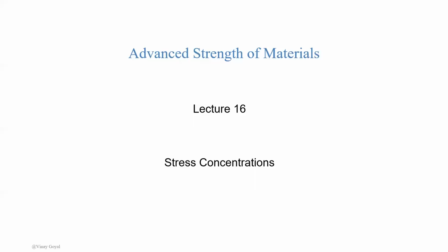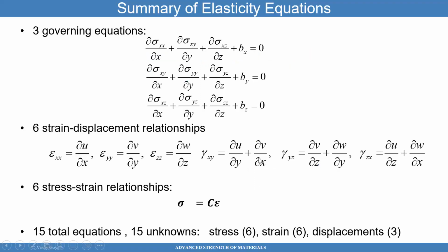We're gonna cover stress concentrations today, and so we're gonna build upon area stress functions that we had discussed previously. And stress concentrations are situations where you have a disruption in the geometry, or you have a material property discontinuity, or there's a situation where that disruption causes a stress riser. Those locations tend to be areas where a crack could initiate, and we have to pay close attention to those.